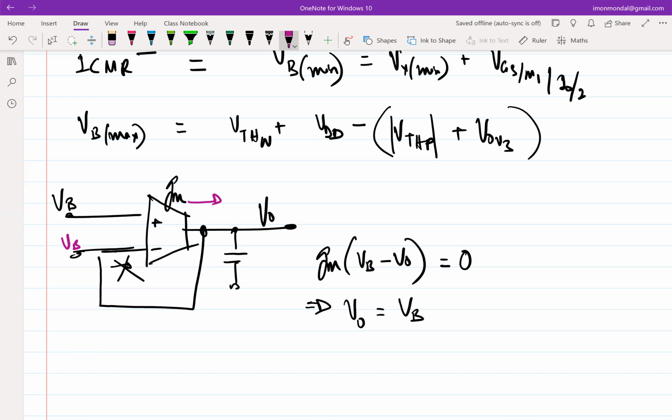So what will be the incremental output voltage, or the return voltage, that it will generate? Don't hesitate, you know the answer. Finite current going into an infinite impedance produces infinite voltage, right? So what is the loop gain at DC then? Infinity. If you have loop gain of infinity at DC, what is the steady state error? 0. So we should expect those two terminals to be equal. Right? Infinite loop gain. Consider this to be an ideal op-amp. So if this has infinite loop gain, it should have 0. Basically, those two terminals are virtually shorted.